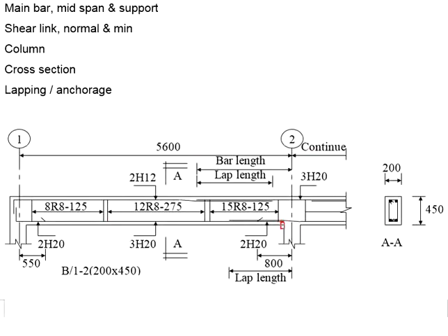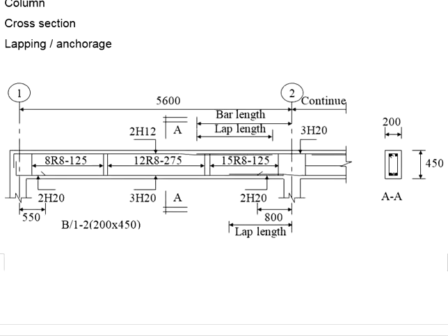Therefore, now your column will be towards the center. The width of the column will be in accordance to the size of the column. You may refer to the key plan or the specifications given. Not only that, you will need to check yourself whether the column stops at this level or is actually going up further.